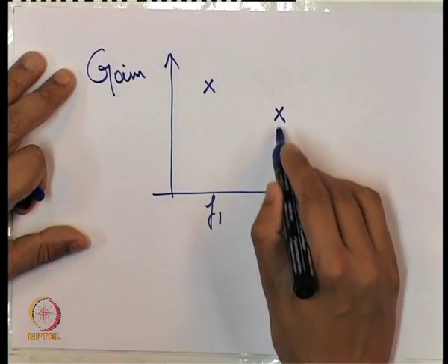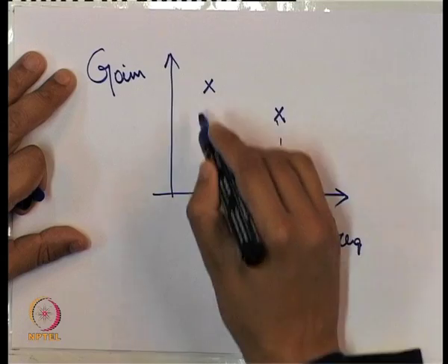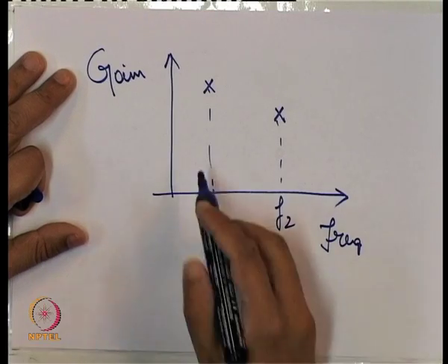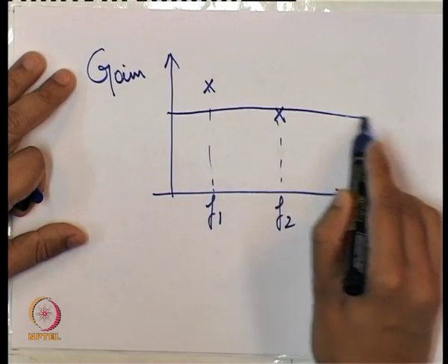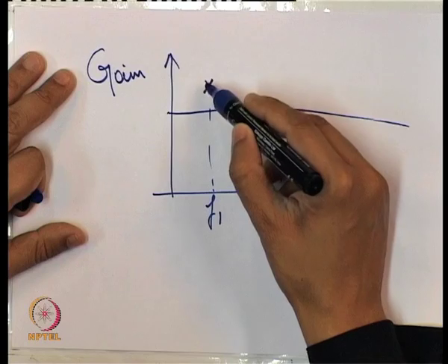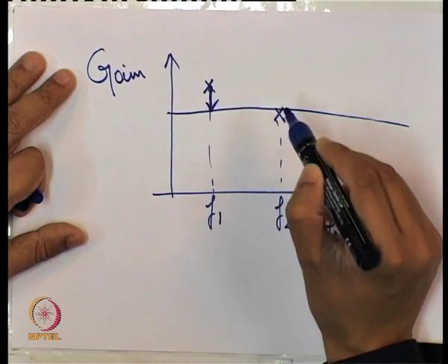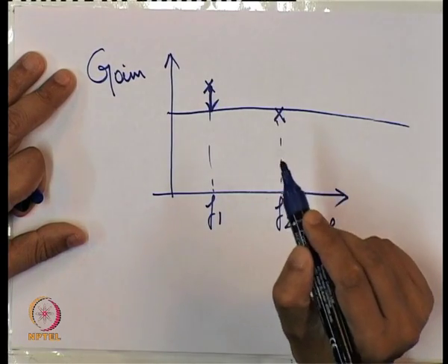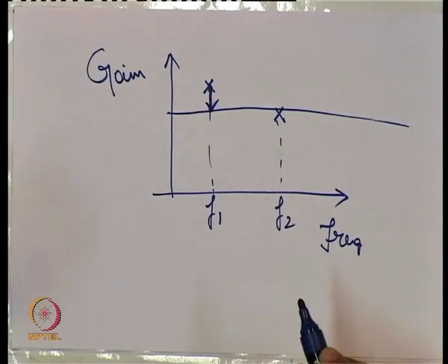At a different frequency I have this as the gain. So, how can I keep my gains constant? One way is to simply use a filter, with a very broad band and bring this gain down so that it matches with the gain of this one at this frequency. This way we are compensating, forcefully making the gain same over the entire range.